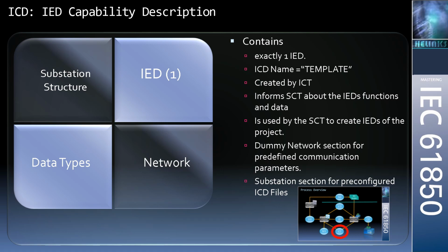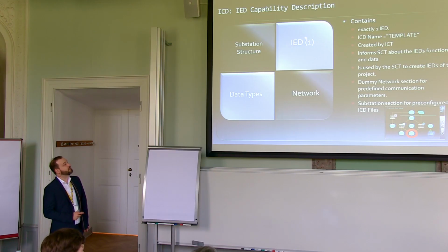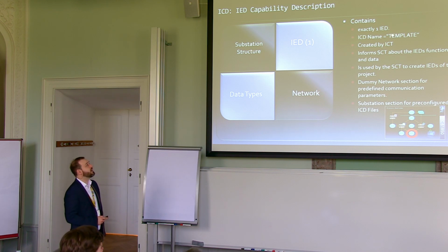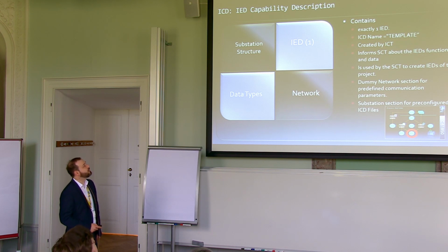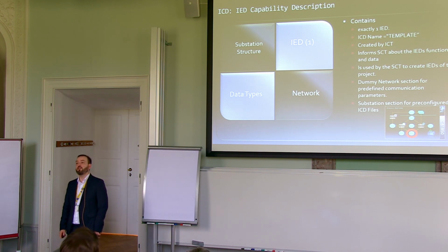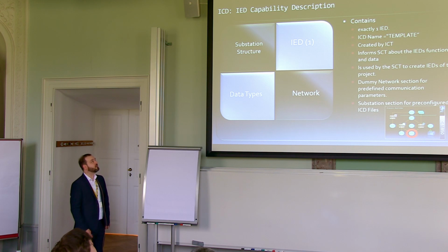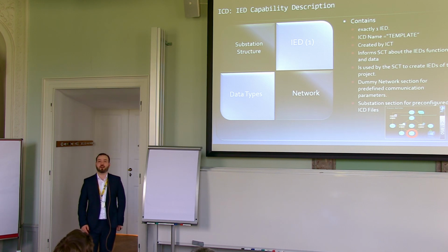Most importantly, they must contain only exactly one IED. And more specifically, that IED name must be template. So if you get handed some ICD files and your tool does not recognize them, it may be worth looking inside and seeing if they actually are ICD files.